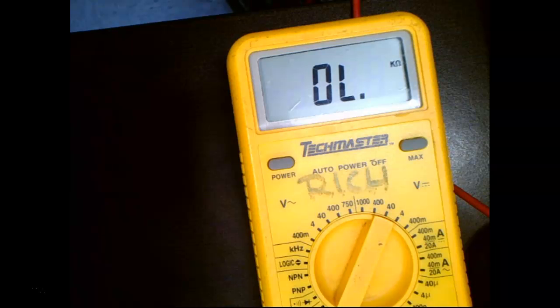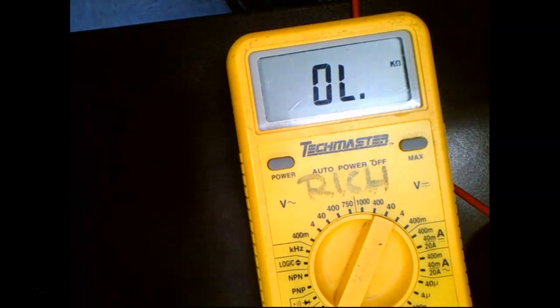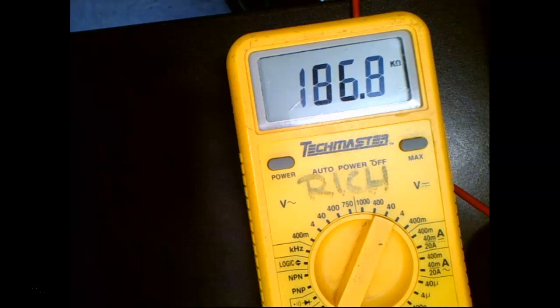Now, on that, I think it would probably be difficult to see if it's a germanium or a silicon. Oh, yeah, if I had a silicon diode to compare it against. Notice a while ago it was 200 and something K, right? But when I measure this in forward bias, it's only 17K. So it's a lot lower. And when I flip it around, this guy is measuring in both directions. One way I was measuring 17K, this way I'm measuring 300 and something K. So that's the big high ratio.